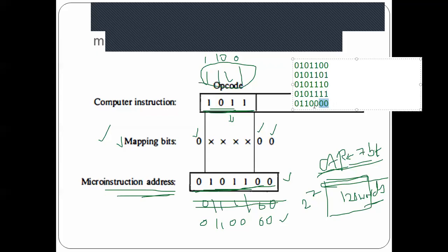Okay, so this is the next address which is dedicated for another subroutine. Am I right? Yes, ma'am. So the facility is given here for provision of only 4 control words. The mapping is like this. In this example, each subroutine may have a maximum of 4 control signals, 4 micro operations.